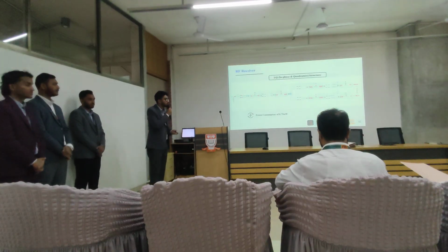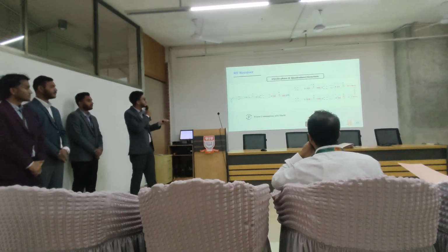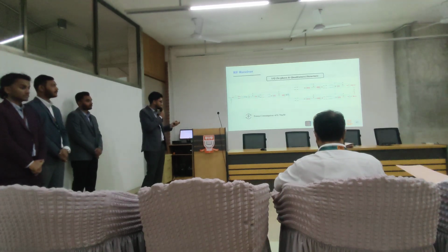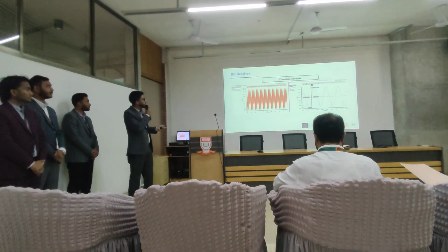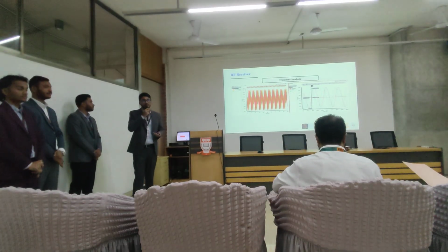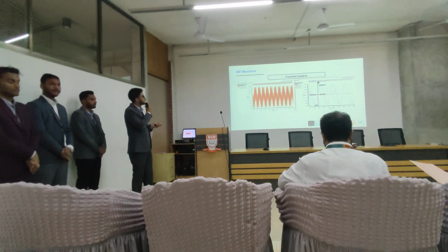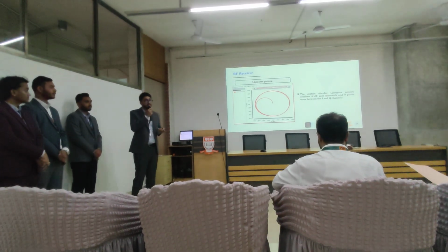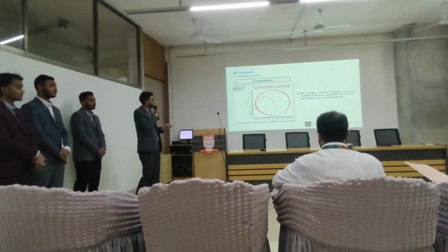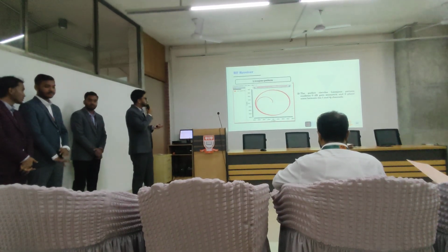Here we show that our power consumption is increased slightly because we add another mixer and another LPF in the Q-phase structure. To verify this, we performed a transient analysis and found that our output has a perfect 90 degree phase shift. After that, we analyzed the Lissajous pattern, which shows a perfect 90 degree phase relationship because we find a perfect circle in the pattern.